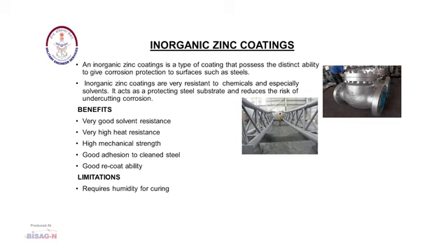Its multiple top coats are used for offshore structures, ships, industrial plants, refineries, tanks, bridges, etc. Benefits: very good solvent resistance, very high heat resistance, high mechanical strength, good adhesion to clean steel, good recoatability. Limitations: requires humidity for curing.